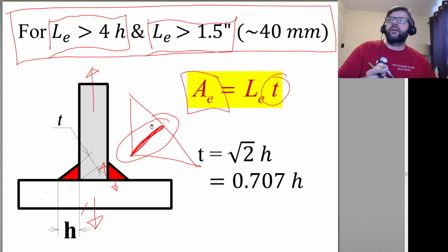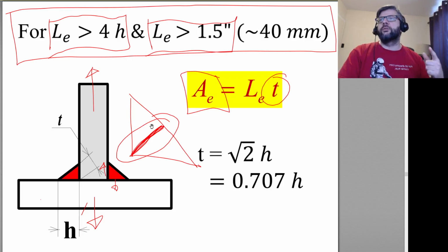If you'll recall the way Mohr's circle works, for a ductile material, if you have a shear load of a certain amount, when that load reaches half the yield strength, that's when you expect there to be failure in yielding.